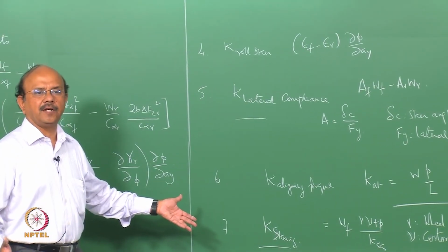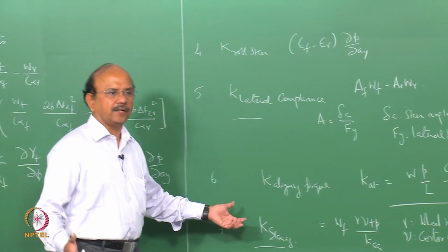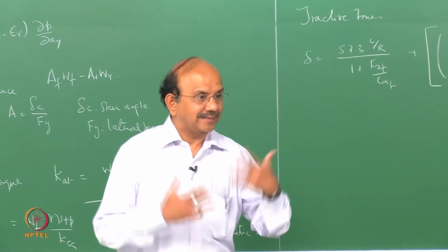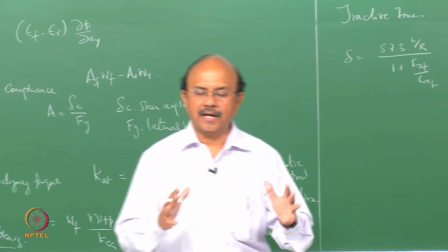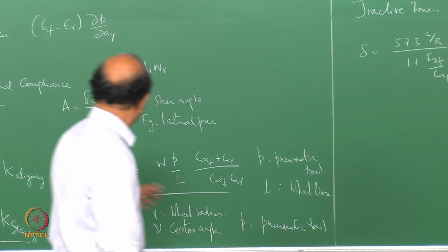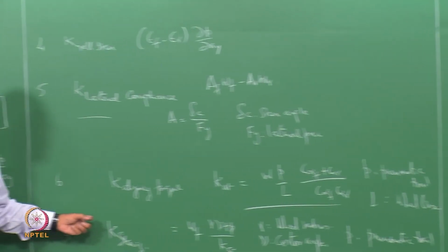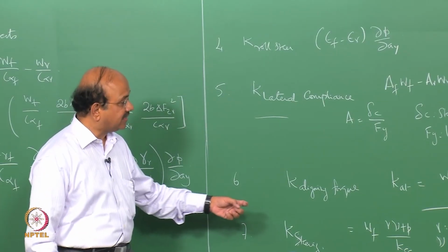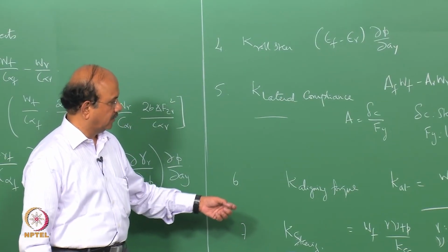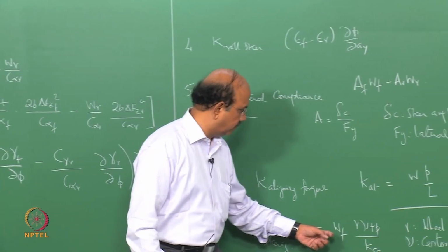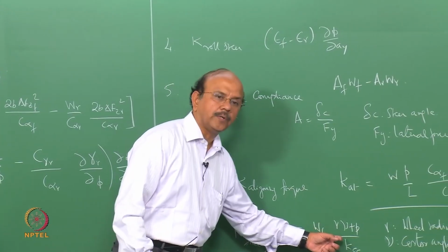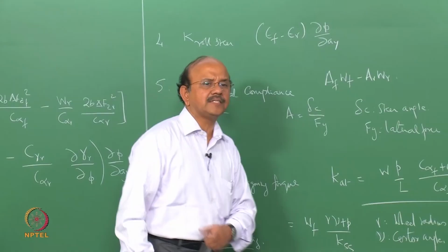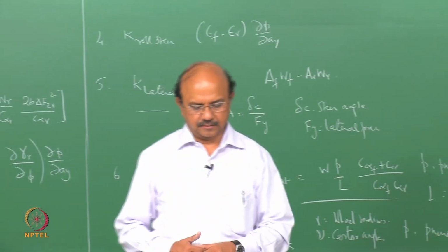Steering participates in understeer characteristics of the tire. Okay, so in other words, that being the input, steering has its own role to play. So the K steering, or the understeer gradient due to steering, has an important component, which, of course WF is known, we call as KSS.